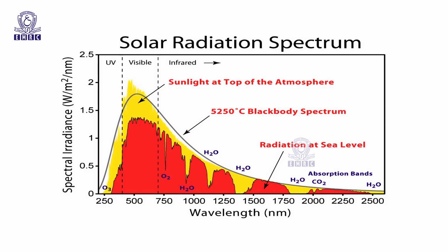The signals detected by passive sensors can generally be altered due to the atmospheric effect, especially in the shorter wavelength of the solar spectrum that are strongly scattered by the atmosphere. These effects can be minimized by collecting data only under very clear and dry atmospheric conditions. Sophisticated atmospheric correction routines now exist to remove atmospheric effects from the data acquired by passive sensors.